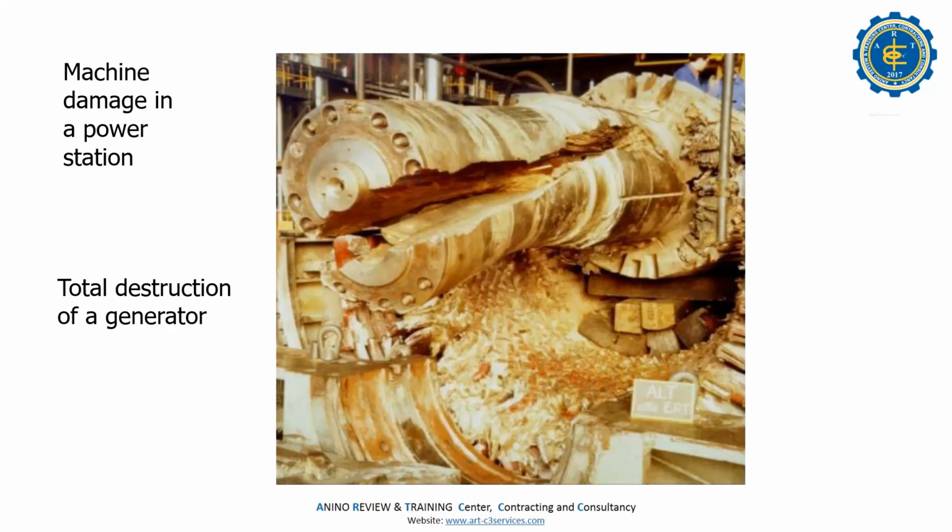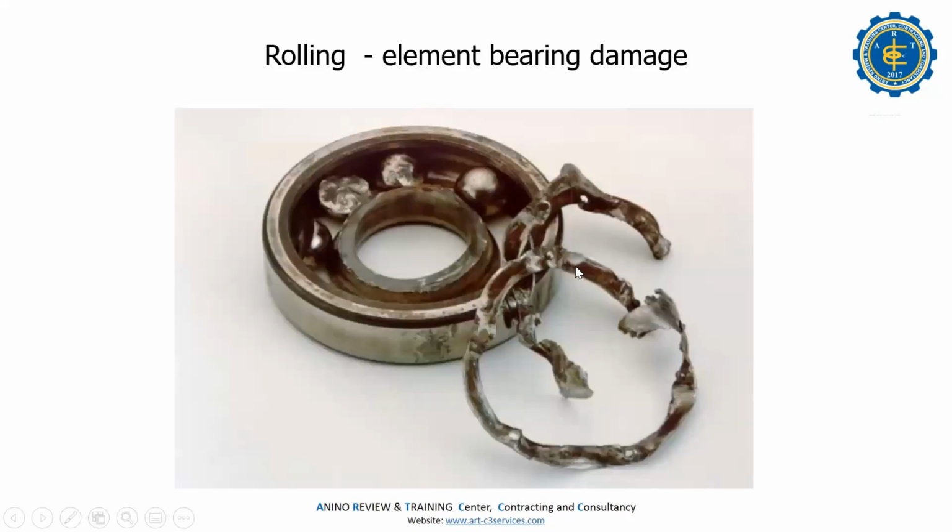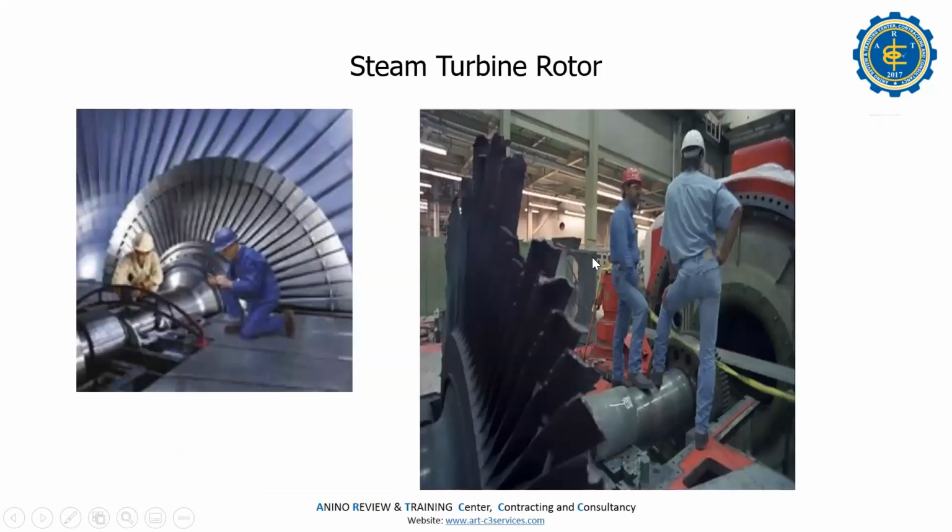So make sure that from time to time you go around with your system, if you have Bentley Nevada, because that's your brand system. Daily you can ask operations or the instrument department, because the instrument department is the one who enables and disables the protection. So this could be the result if there is no monitoring of the plant: bearing and turbine rotor damage.